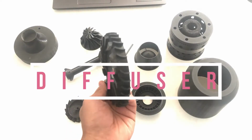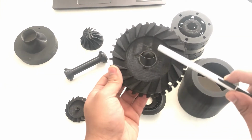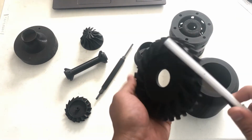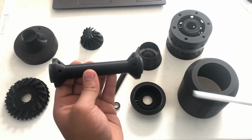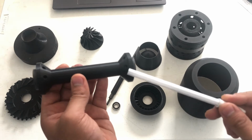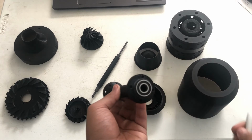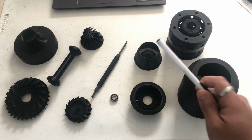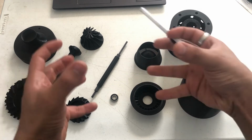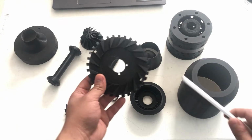The diffuser redirects compressed air to the combustion chamber. These holes are made for the oil and kerosene pipe. The shaft housing protects the shaft and bearings from hot kerosene gases and distributes the oil through these holes to the bearings to keep them lubricated. If you wish to build your own real jet engine, keep in mind the necessary screws to keep the engine joined. That is why the diffuser has holes along with the holes in the shaft chamber.